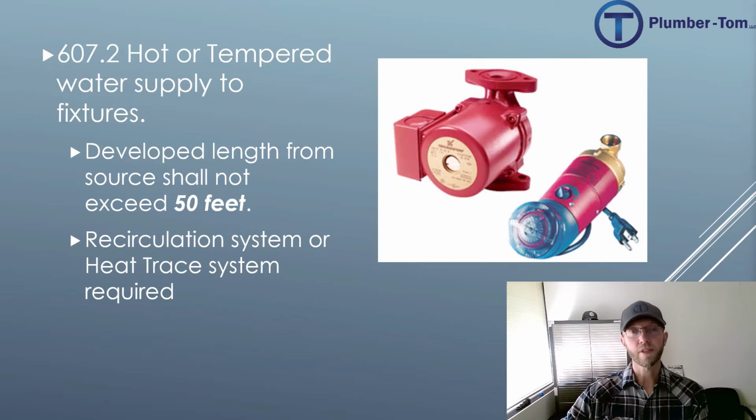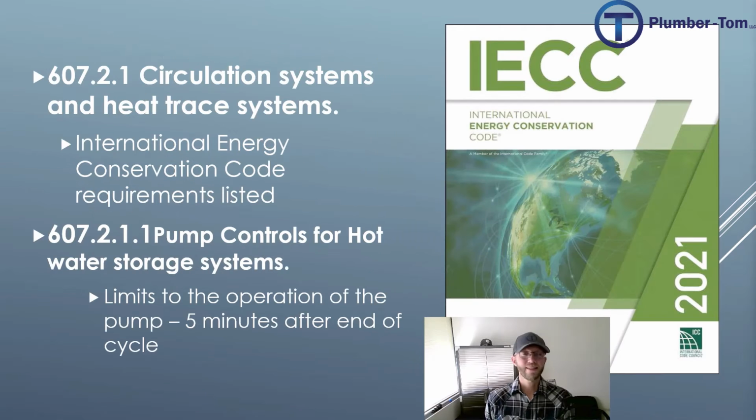Now there's two options for getting that hot water out to a fixture quickly. One is a recirculation system where a pump is pushing that hot water out and bringing it back to the water heater. The other is a heat trace system. In 607.2.1, the code refers us over to the International Energy Conservation Code and gives us a number of standards from that code that these recirculation systems would have to meet.